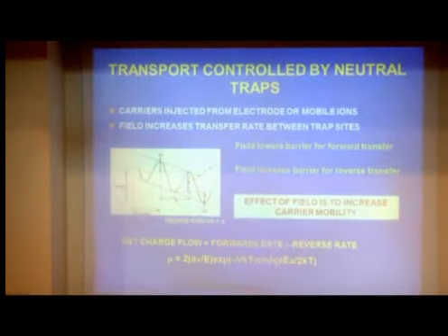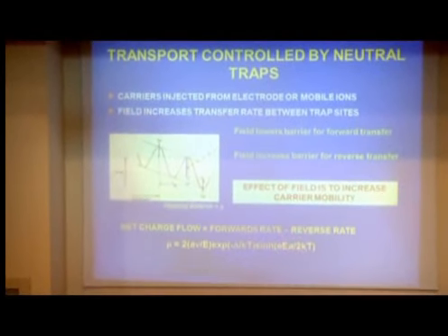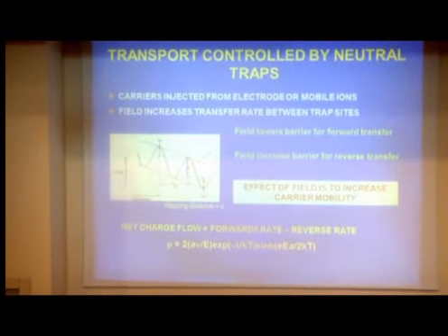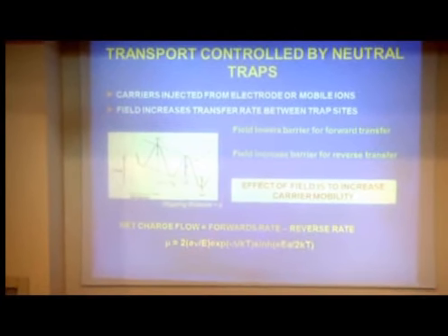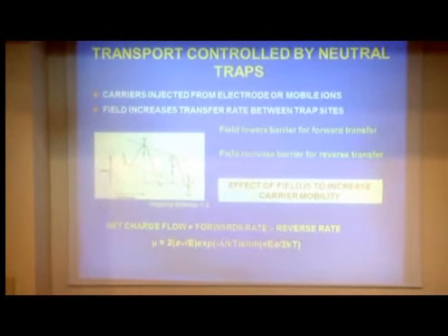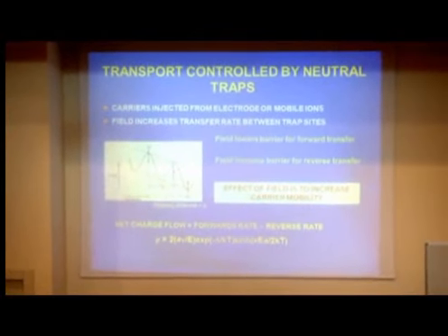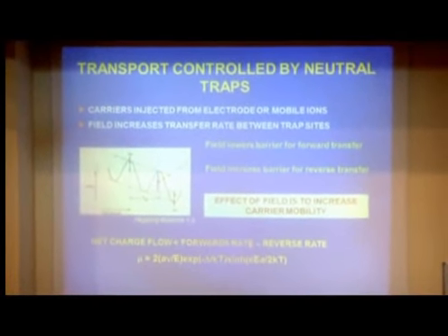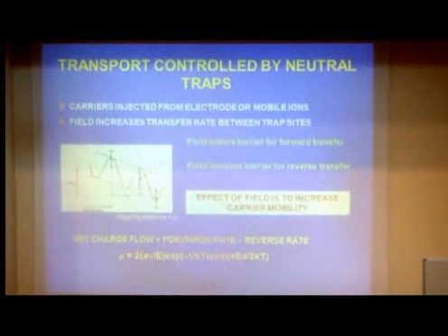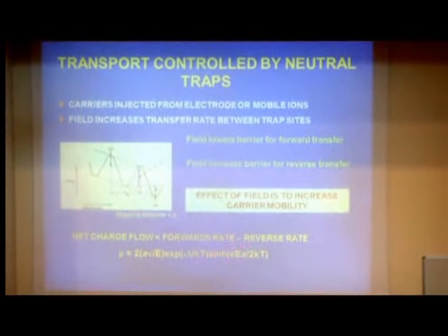What we can see is that at low fields, so that this term is small, the sinh term reduces essentially to this term, and the field in here cancels with the field down. So you reduce to the standard Mott expression for the mobility. When we have a high field, the first exponential term of the sinh term dominates. So the mobility increases exponentially with the field.